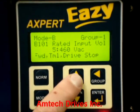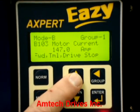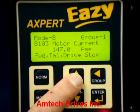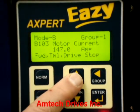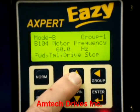Again, your rated input voltage, the motor voltage, the motor current. In this case, it's set for the default on the drive, 147 amps. By setting this, you set up the overload protection for your motor. The motor frequency, 60 hertz.